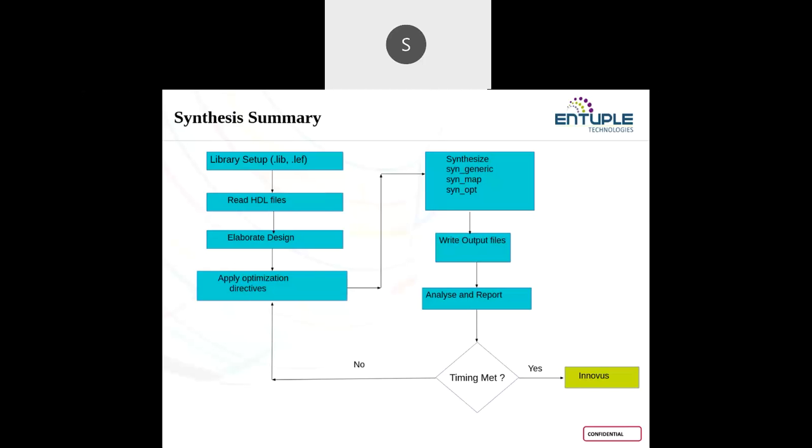The first question is, which algorithm is used for binding and mapping? See, the backend tool is calling scripts that are already written. Usually that information will not be given, but I can say the mapping is a command which helps me map the standard cells available from the library. I am just making use of the commands available in the tool. Which algorithm is used in the backend will not be shown here.